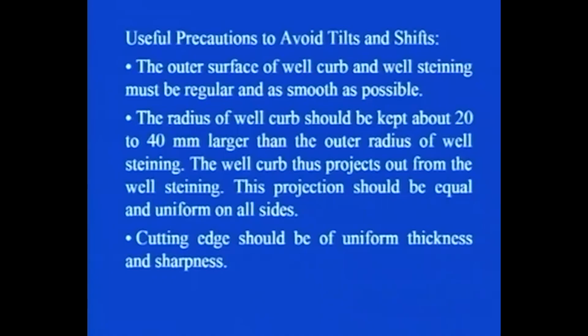The various useful precautions which are to be taken to avoid tilts and shifts are that the outer surface of the well curb and well steining must be regular and as smooth as possible. So if it is quite smooth, the tilts and shifts are relatively less.